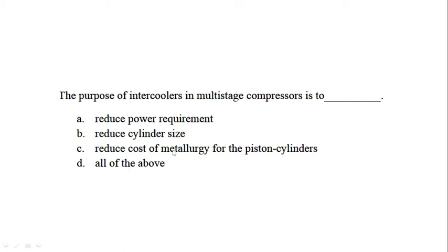So for removing that, we need to use a vertical vessel, which can handle a high vapor to liquid ratio, but a horizontal vessel can handle only a low vapor to liquid ratio. So the separators are mainly vertical vessels. And the horizontal vessel is used in extraction; after extraction we'll get some foaming liquids. So after the extraction stages, we find mainly horizontal vessels.